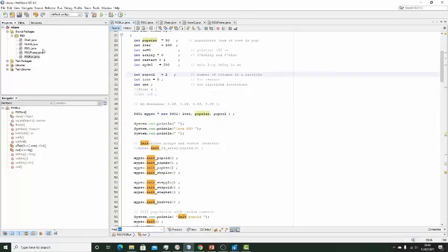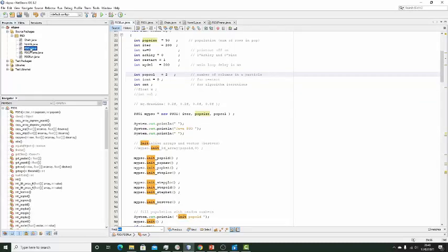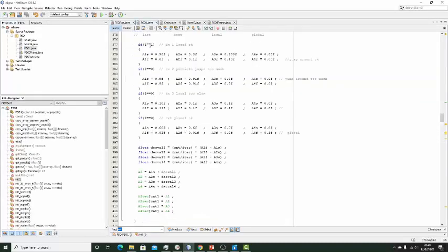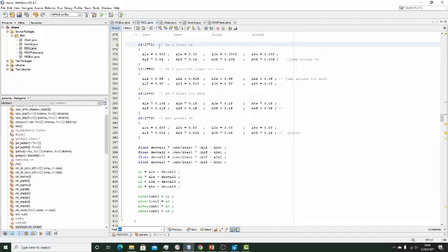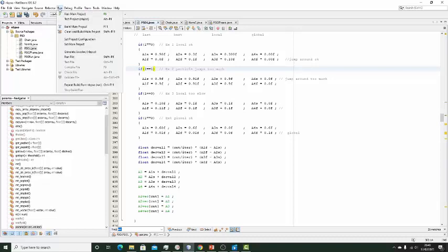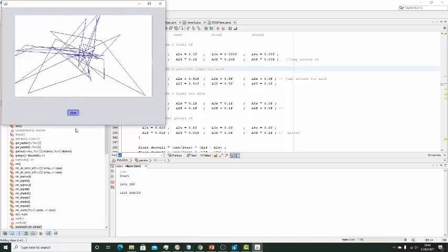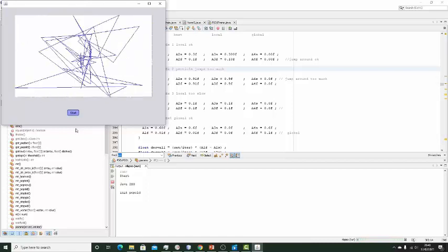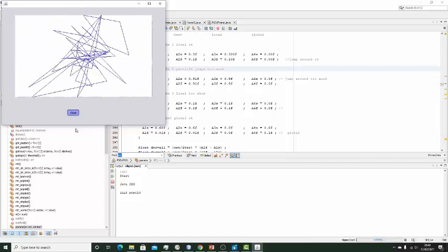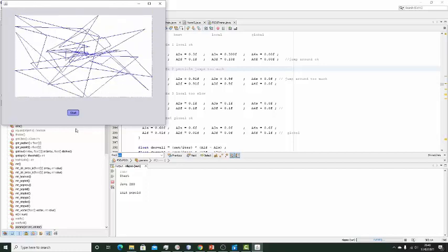What I'm going to do now is switch across to a different function and turn off the first set of options and look at this option. Sorry, put a 1 in there. Here we've got quite large values for the variable A, and this causes the system to oscillate. So clearly, if you set the incorrect value for the A term, then you may not get a satisfactory solution.